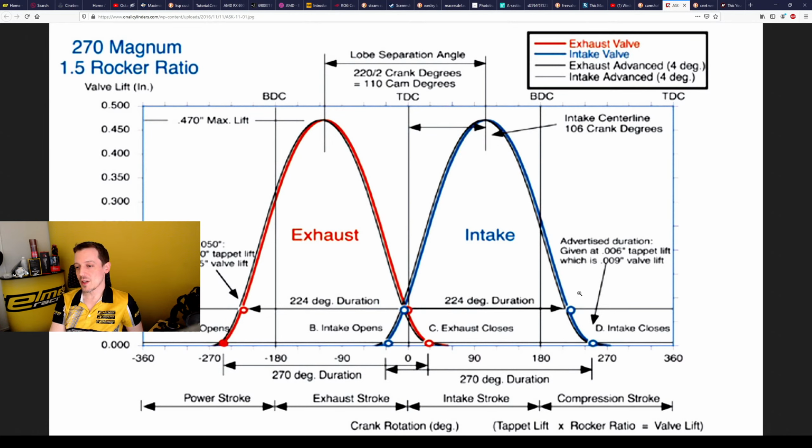But that definitely sounds like a very good solution, because I do think that with pneumatic stuff you can probably get higher power density than with hydraulics, because you have so much viscosity with hydraulics that if you're trying to open a valve very quickly with hydraulics, then that might be difficult. I mean, you can use a very high force over a period of time to have really good power density with hydraulics, but doing something extremely fast, then the viscosity will end up creating problems. So it does make sense to do that.